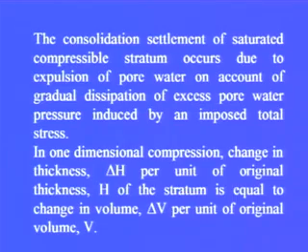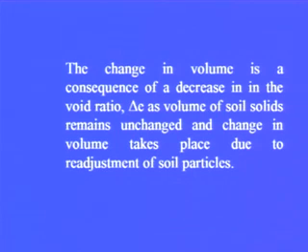So, using this data, we can obtain the parameters and then calculate consolidation settlement. The change in volume is a consequence of decrease in the volume of voids, that is, change in void ratio delta e, as the volume of soil solids remains unchanged and the change in volume takes place due to readjustment of the particles. As water escapes out from the voids, these soil solids are readjusted and we get a compression.